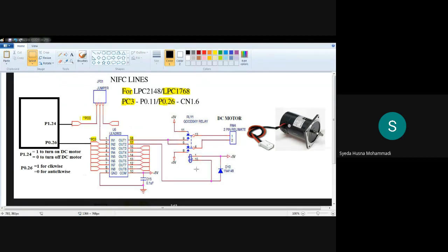It depends upon this diode here. You need to energize this particular diode. Just see the connection here, where this diode is connected to. This diode in turn is going to energize your relay. You can see it is connected to PC3. So we have to find out where this PC3 is connected to. I'll show you where PC3 is connected.